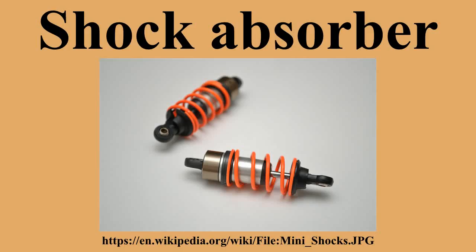In very heavy-duty units used for racing or off-road use, there may even be a secondary cylinder connected to the shock absorber to act as a reservoir for the oil and pressurized gas. In aircraft landing gear, air shock absorbers may be combined with hydraulic damping to reduce bounce. Such struts are called oleostruts.